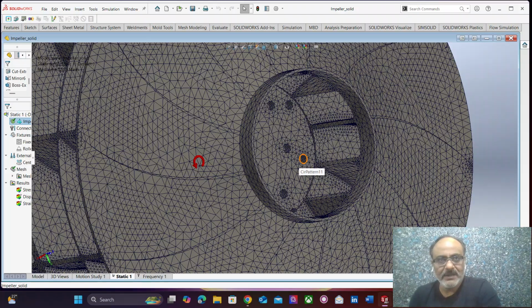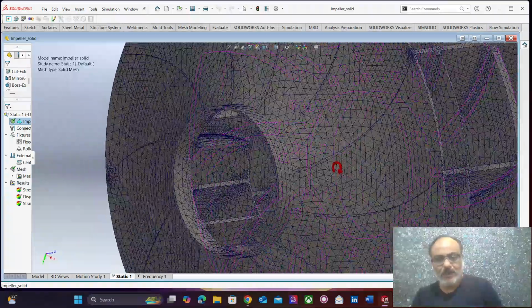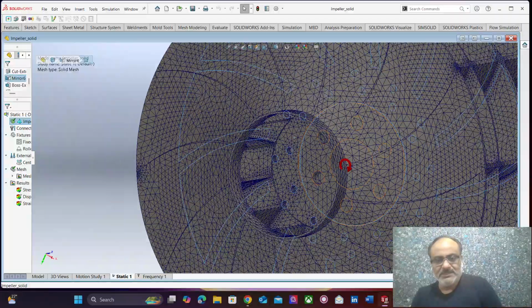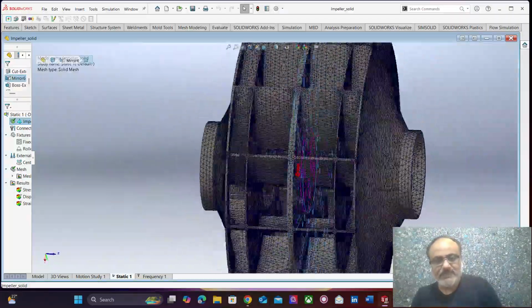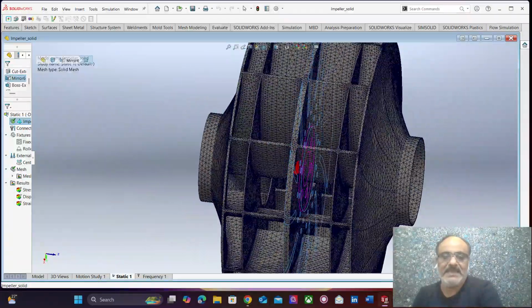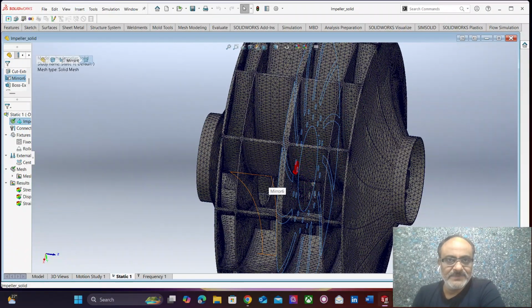Now we had removed certain material from that, and we have assumed about 15 mm thickness, and to that 15 mm we have added another 5 mm in the form of 2 plates, on this side as well as the bottom, the opposite side. So the central disc is reinforced with 2 different plates on either side.